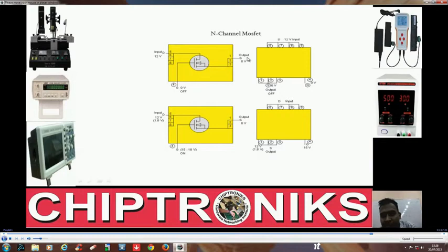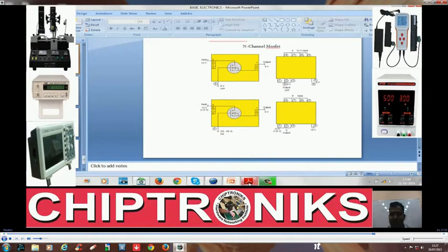This voltage will not appear over here, because if this MOSFET gets turned on, the switch is closed and this point and this point are connected. But here there is 0 volt. So we have to apply a voltage greater than 12 volt and a specified value. That means if we apply a voltage between 15 to 18 volt, then this MOSFET will get turned on. Okay, let us check the schematic diagram to understand it.